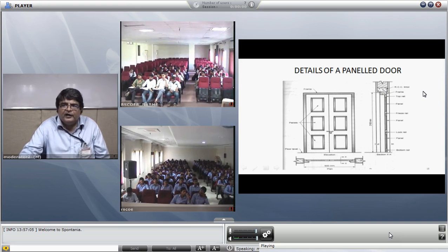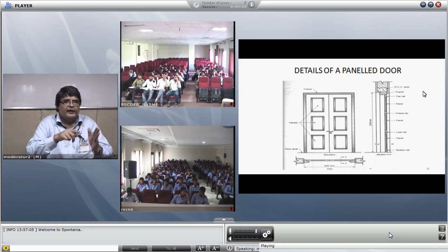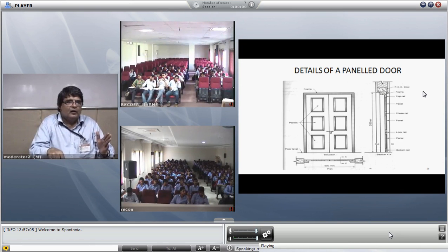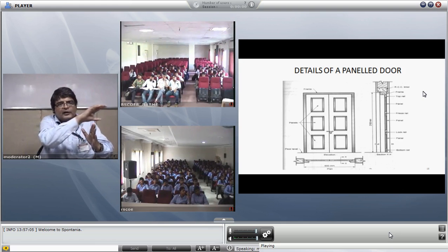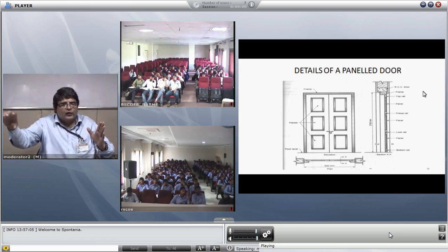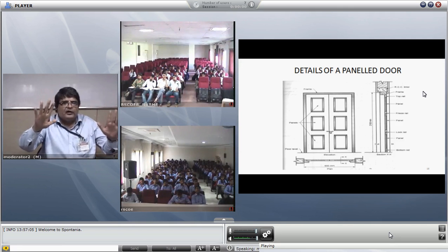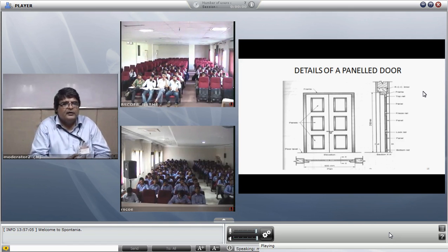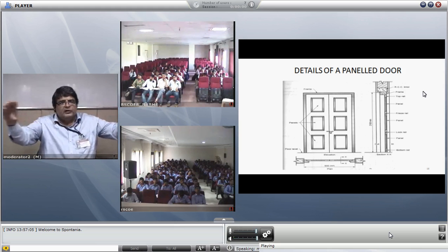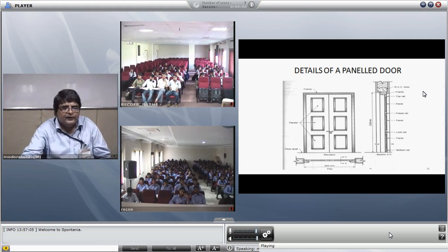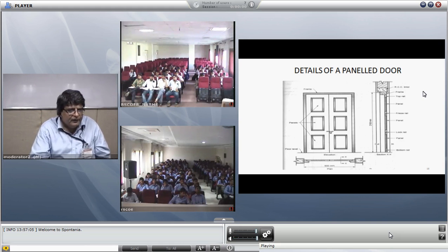the brick masonry above the opening, if you cut a hole in the wall, the bricks above the hole will have no support. Therefore, they must be given some support. If you just put a plank and place the bricks and let the mortar harden and then remove the plank, again they have limited support of the mortar joints. So to give support to the bricks above the opening, something must be done. That's why this lintel is built. And when we come to the lintels and arches, I will show in detail.